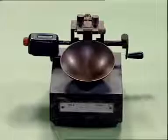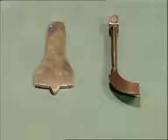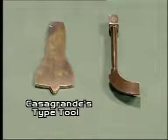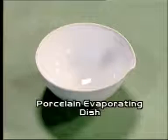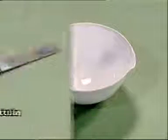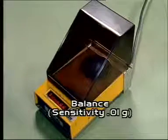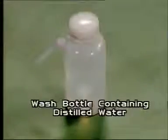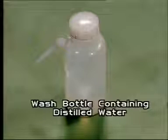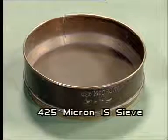The apparatus required for conducting this practical include mechanical liquid limit device, grooving tools like Casagrande type and ASTM type tool, porcelain evaporating dish, spatula, balance with sensitivity to 0.1 gram, thermostatically controlled oven, wash bottle containing distilled water, sample containers and 425 micron IS sieve.